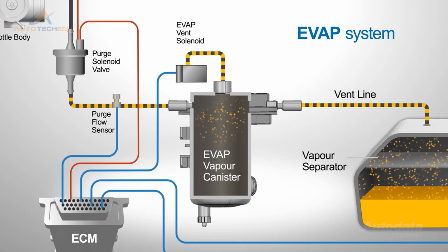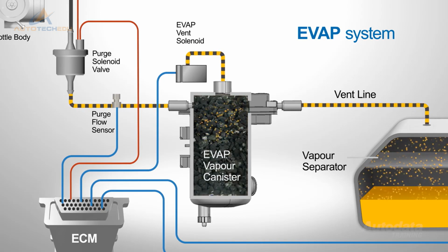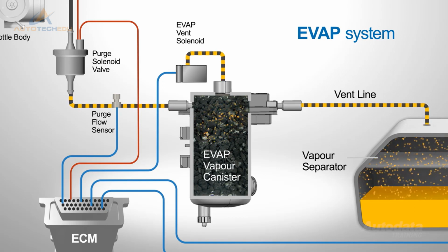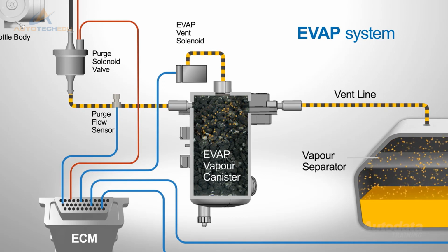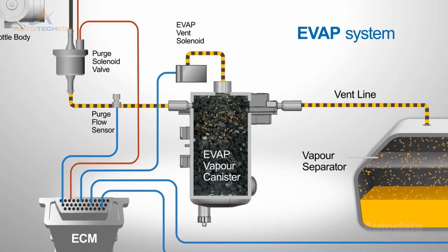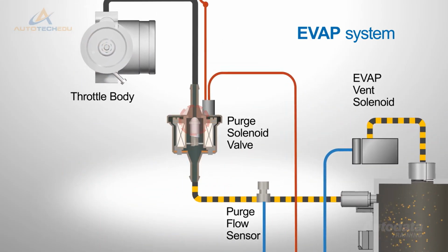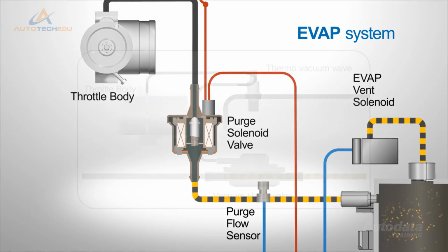The contents of the carbon or charcoal canister is in the form of activated carbon granules. The properties of this material allow hydrocarbon vapour to be suspended within the granules. The canister purge valve is normally in the closed position, holding evaporative emissions in the canister.